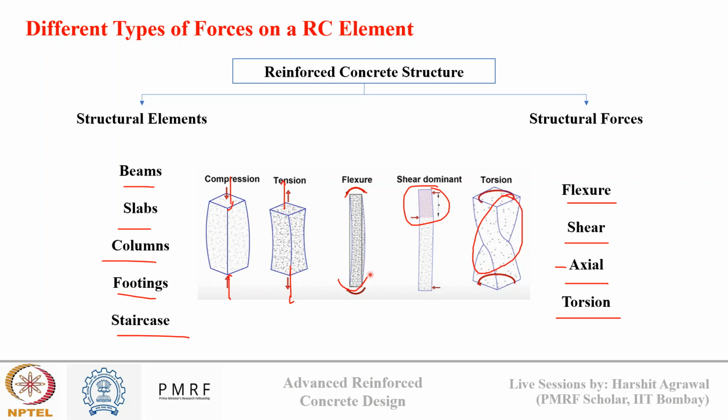So while designing a reinforced concrete element, it becomes important to understand each of these forces, how they are affecting the reinforced concrete, and to make sure that the design system is capable of handling all the applicable forces. It is not like the design system should just be able to handle flexure. If there is shear which is also occurring, it should be able to handle both shear plus flexure. So understanding each of these forces separately is important in that way.